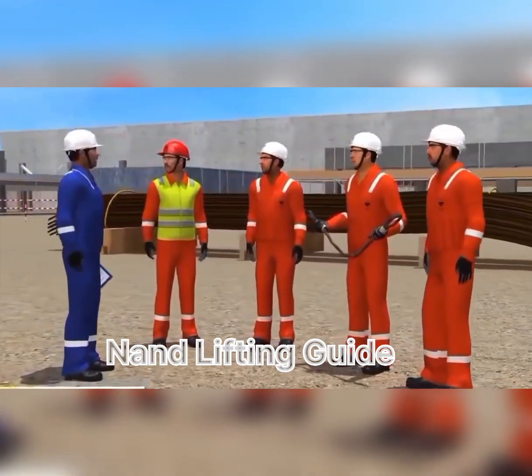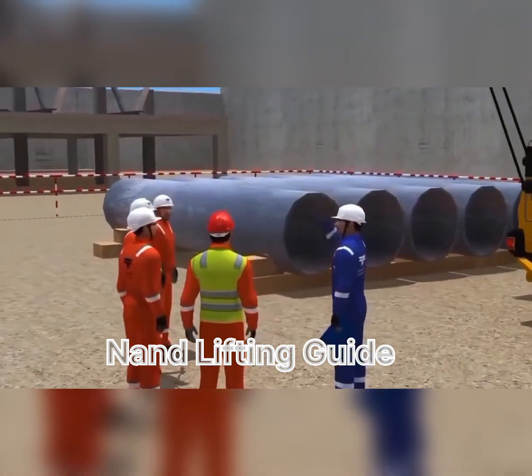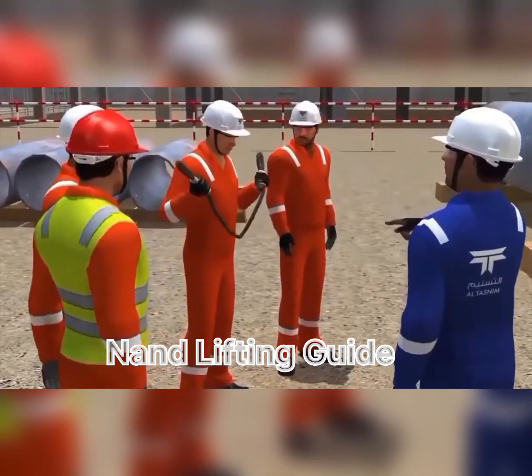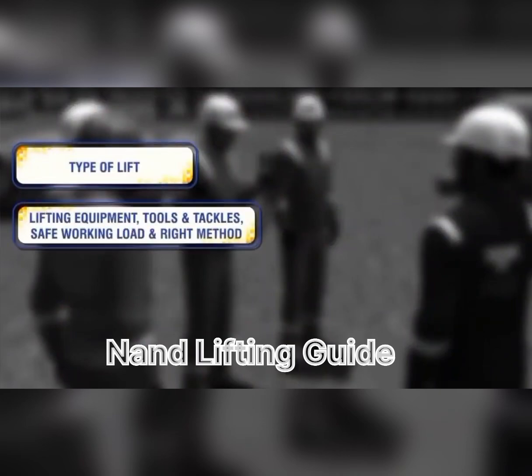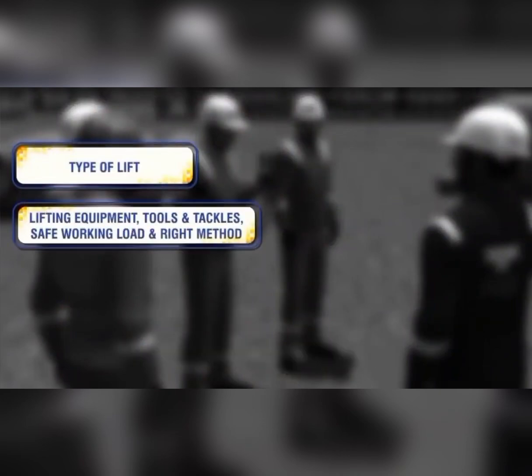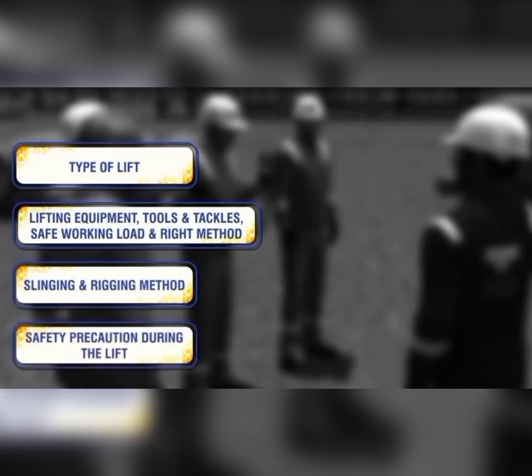Lifting plan. Lifting plan contains the essential information for the particular lifting operation, such as type of lift, selection of lifting equipment, tools and tackles, safe working load, and right method to use them. Slinging and rigging method. Safety precaution during the lift.